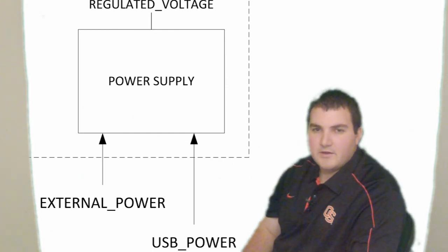The voltage regulator subblock will supply power from the battery pack to feed other blocks that make up the robot. To the best of our knowledge, we will need at least 2 different power rails coming off the voltage regulator subblock to the other blocks in the robot.